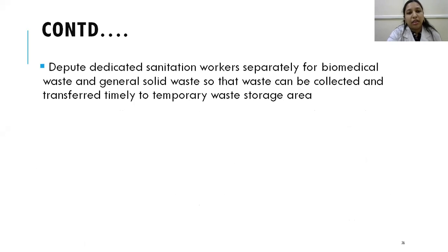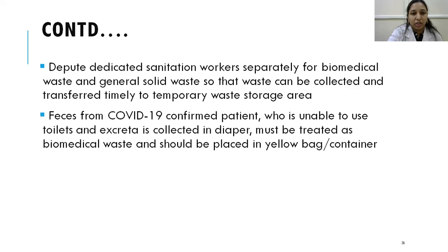Okay, and you have to have separate dedicated sanitation workers for biomedical waste and general solid waste management in COVID-19. So for the transportation and everything, you should not mix them with other waste management sanitary workers. If they are having any symptoms or whatever, such persons should not be used for biomedical waste. So there should be separate sanitary workers for COVID-19 waste transport and storage.